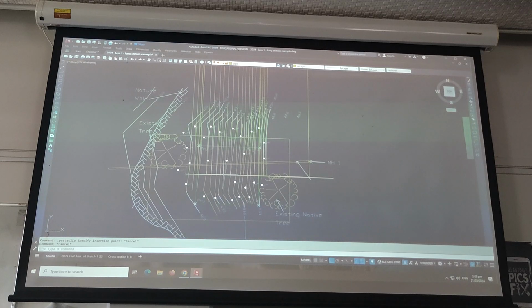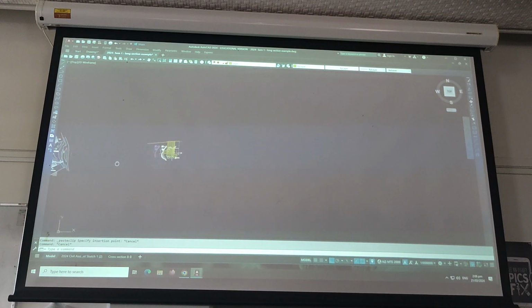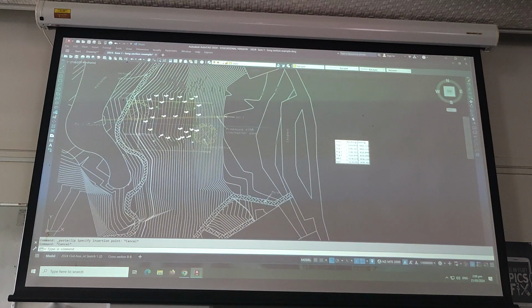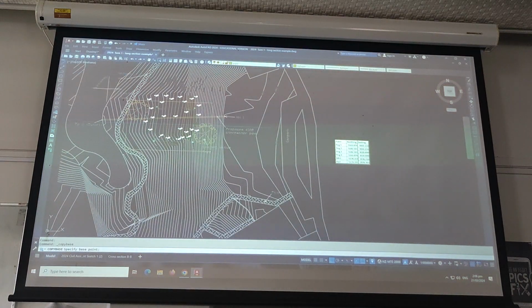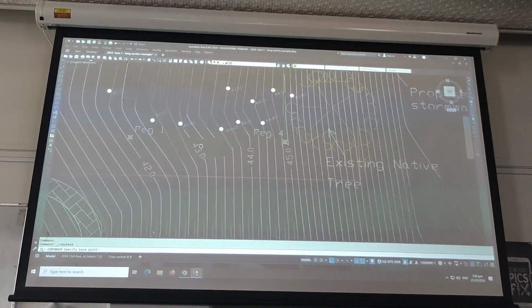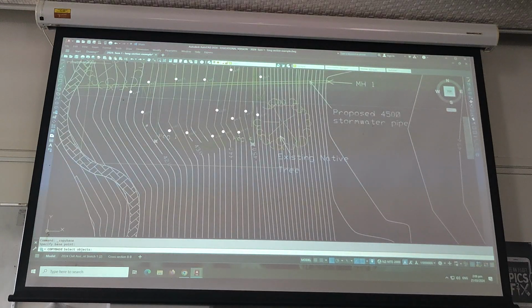That didn't go far enough. I need a common point. Edit, copy with base point. Pick 1. And we'll copy 4 of these.